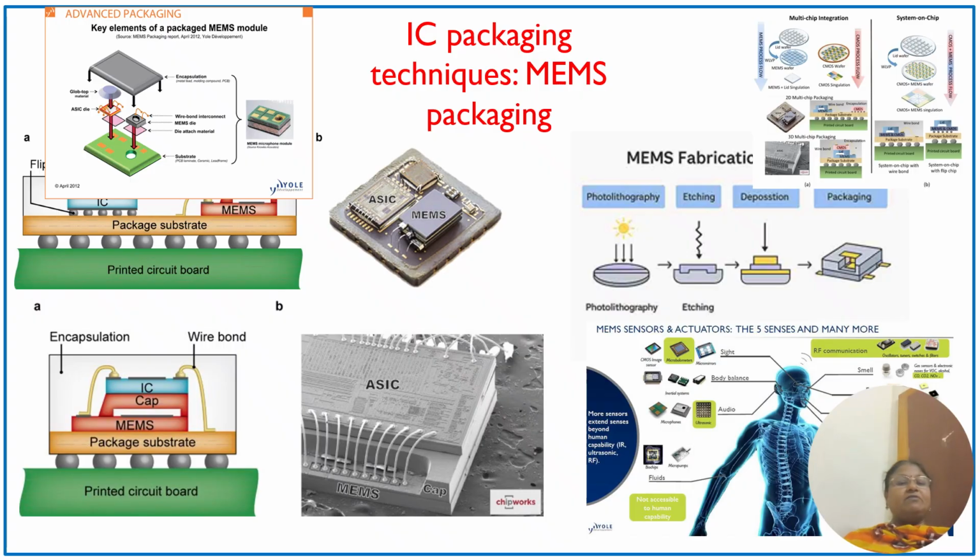Now look into this advanced packaging unit. The key elements of a packaged module look like this. A printed circuit board, and you can see these walls, which are nothing, it's a connectivity established, and this is a package substrate onto which you can have an IC, you can have one MEMS design, and all these are going to be flip chip packaged. That is advanced packaging technology.